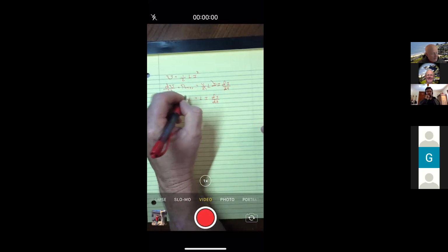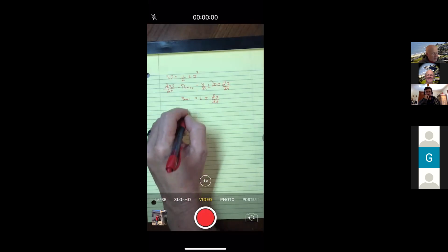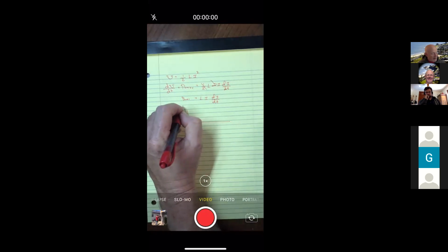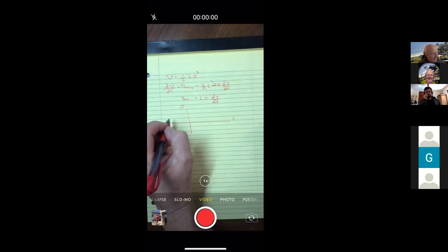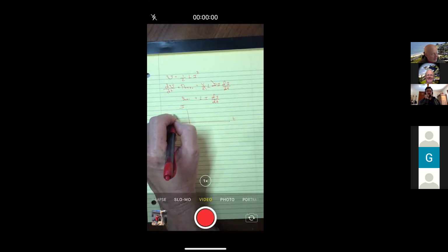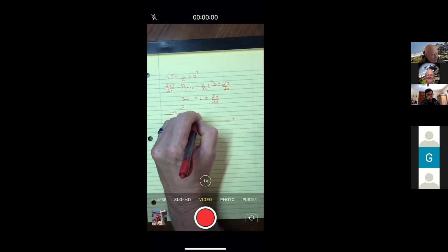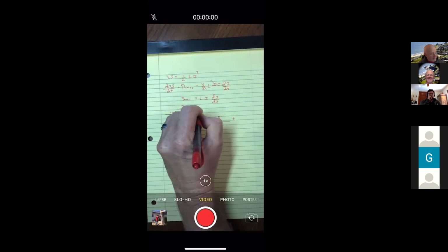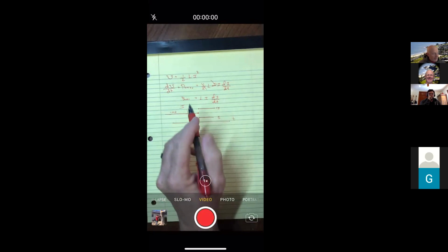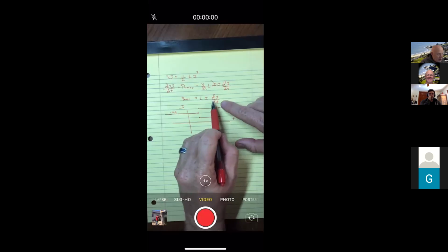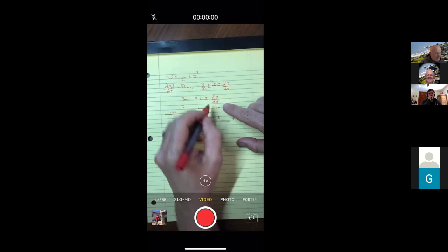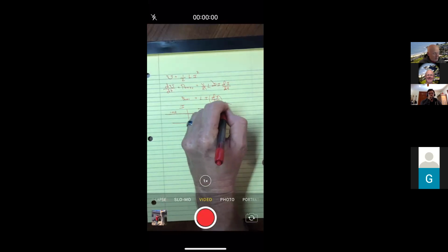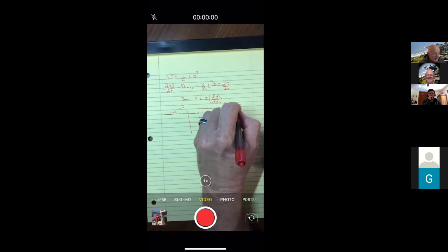This would say for the current to change instantaneously. So let's say you had a graph that says current versus time, and let's just say the current was, I'll just pick a number, 10 amps. Could it instantaneously reduce down to 5 amps or instantaneously jump up to 15? And this is saying to change instantaneously, that di dt would have to be infinity.